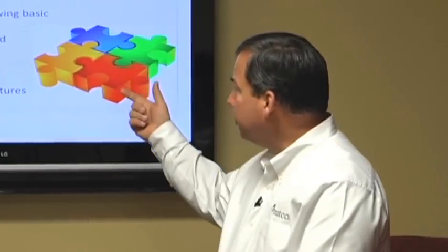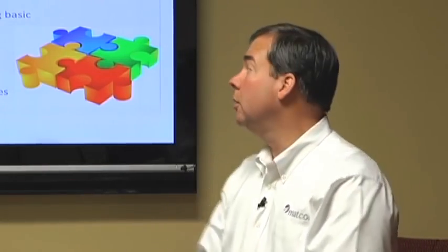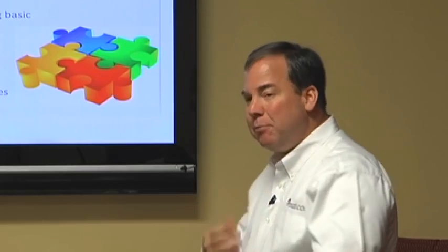So you need a structure to protect. You need an electrolyte that current can flow through. Obviously, you need some sort of an anode to deliver current. These are my lights that are going to light up the structure. And then there's some cabling in there to connect it because you have to have that metallic path or that circuit, okay? So you have to have something connecting the anode to the structure. Often there's multiple connections of the anode to the structure.